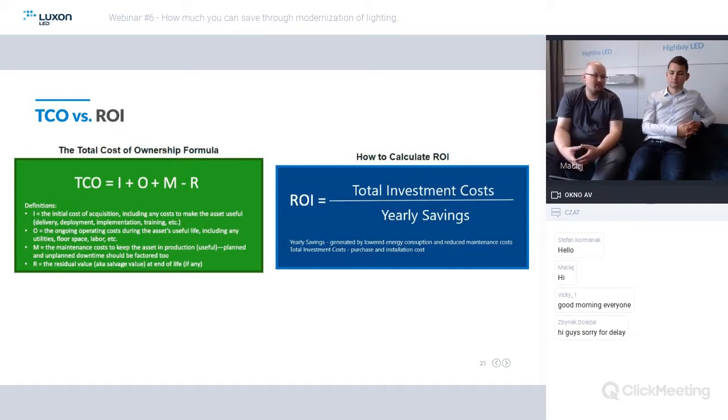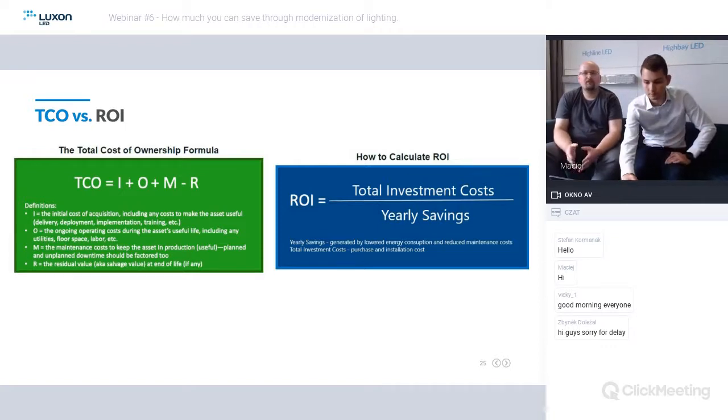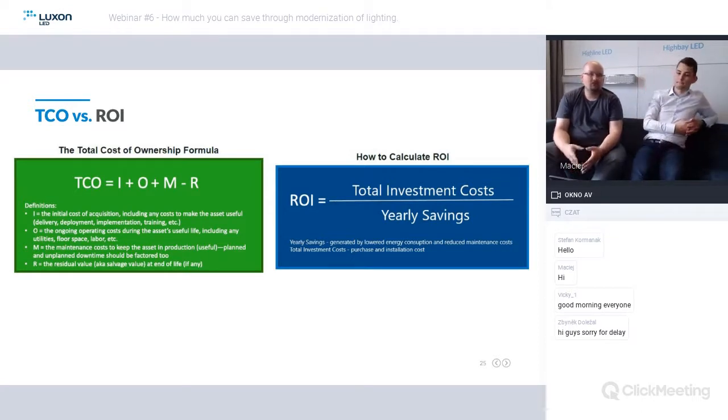For LED luminaires, maintenance costs are very low. Sometimes they are even close to zero, because with traditional lighting you had to change lamps, check the luminaire status, whether they are working, whether the fluorescent tubes are okay, etc. Today, if you take into account an installation with intelligent luminaires, so DALI, you can have flags that give you the information that a luminaire stopped working or the light source is used up, so you don't have to waste time, energy and money on manually checking the luminaires.